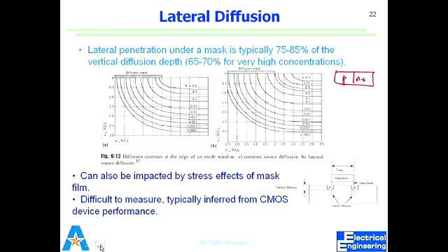I have a question on cleaning actually. Cleaning? All right. When we do RCA clean, why do we need to heat the solution before we? Interesting question. This is to speed up the reaction. Other way would be to use more sulfuric acid to make it more exothermic. Not only sulfuric. Okay, piranha is hot as is. Once you mix it, it's hot. But what about the other one? So just to use less acid, we heat it externally.